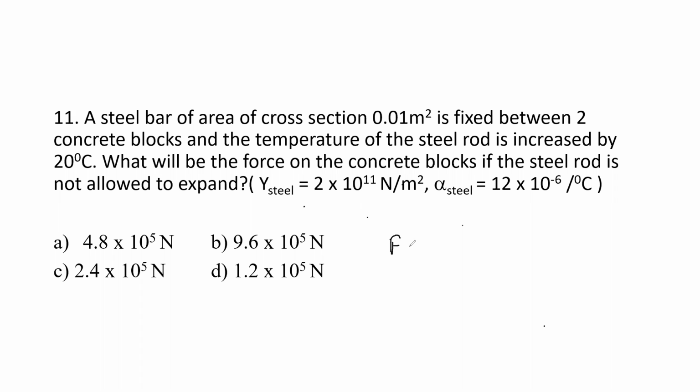It is given by F is equal to 2 into 10 raised to 11 into 0.01 into 12 into 10 raised to minus 6 into 20. If I simplify this, I'll get 4.8 into 10 to the power of 5 Newton. That is option A, the right option here.